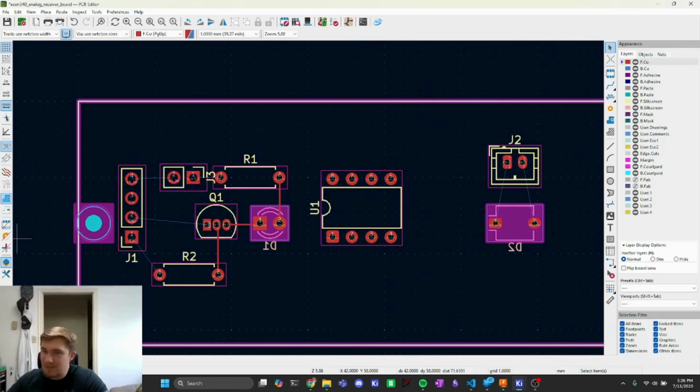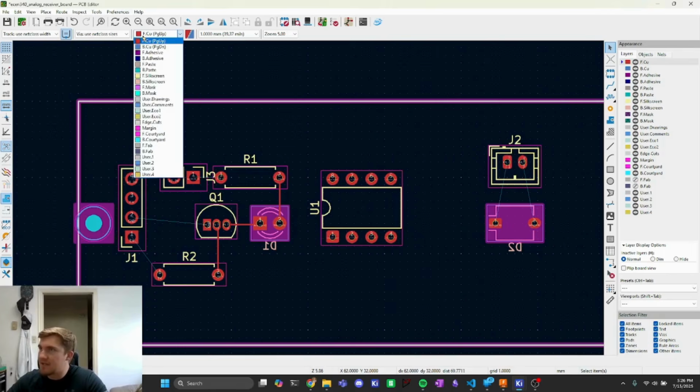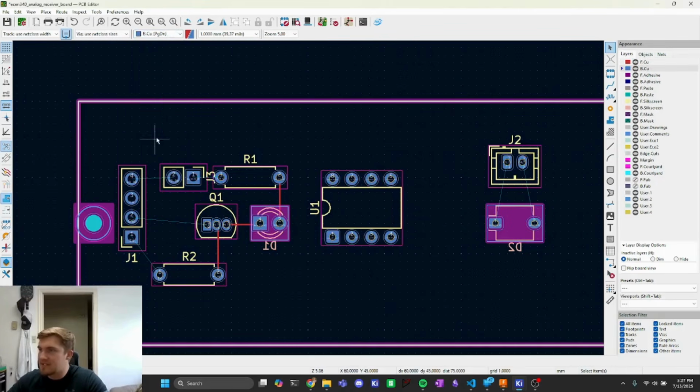Your board is made out of 2 layers of copper. The front layer, which we see here in red, is prefaced by the F, and the back layer is prefaced by B, which is the blue layer. All of our parts intersect with the front and back layers because they're through hole. They punch all the way through the board, so they have a little bit of copper that's front and back on it. Everywhere that you see black, there is no copper.